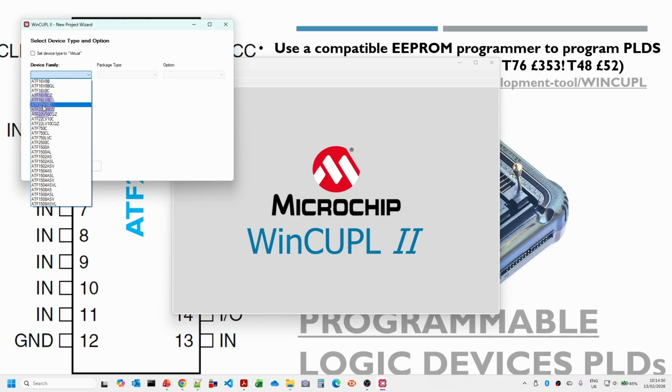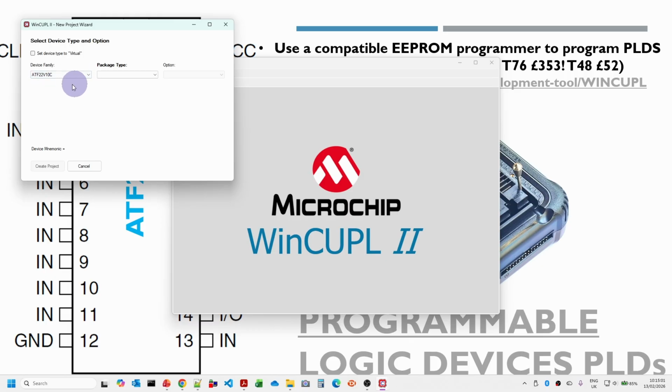So we've got an ATF22V10C. It is important to make sure that you match the exact model here, because there are differences between the different models, with different capabilities. We've got the 24-pin DIP, that's a dual inline package. That's our breadboard compatible. You can see there are various other flat pack forms. And then there are some options here. This is the power down mode, and I think there's a user extension area where we can put a few bits of information, but we don't need to use that. So we're going to create the project.